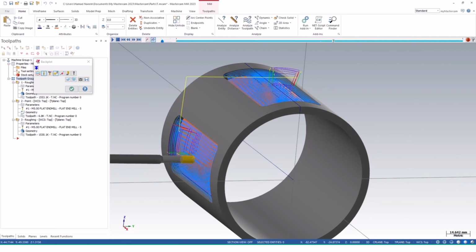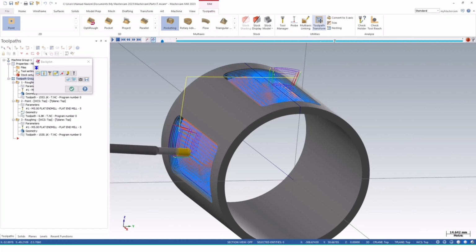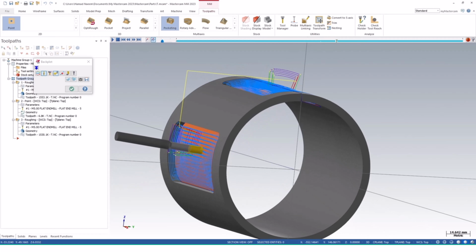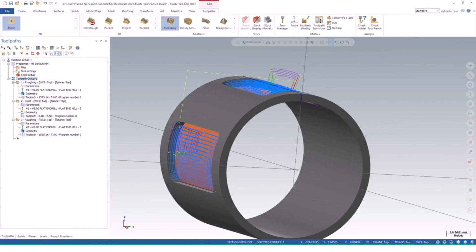After doing the toolpath, we transform the toolpath using the transform toolpath method, and we got an error. So for removing that error, we just create a point of reference where the tool will go back and then move to the other toolpath location. Okay. So this is how we can create multi-axis toolpath. Hopefully you enjoyed that video, and stay tuned for more videos. Thank you very much.